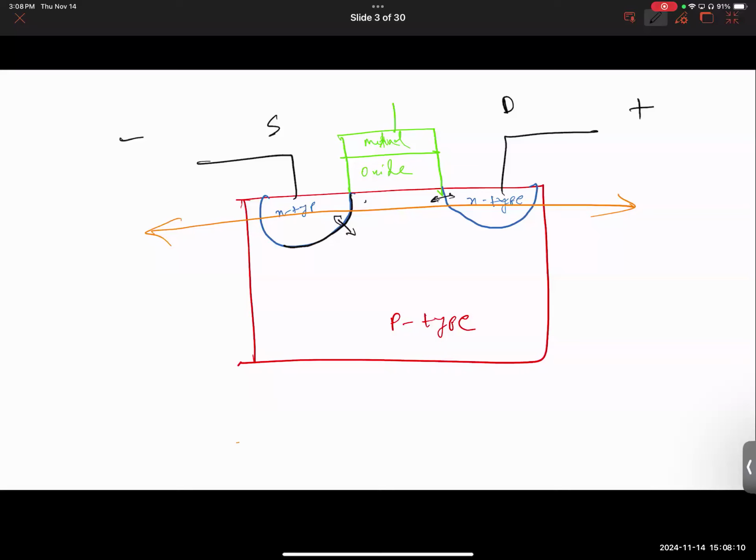Now, if you apply a positive voltage to the gate, which we have been doing with inversion and whatnot, the holes in the P-type layer will run away from the surface deeper into the body. The body is typically much deeper to allow that migration. So now you end up getting what? Remember inversion?